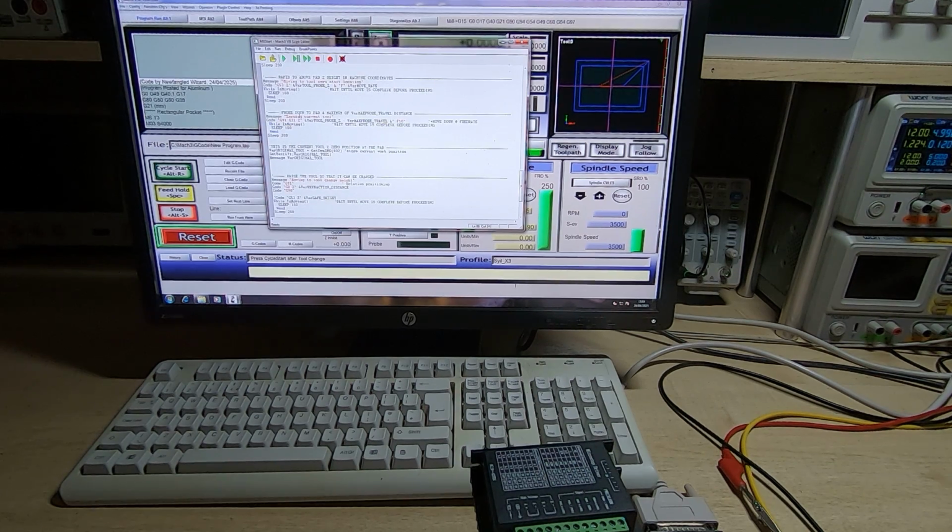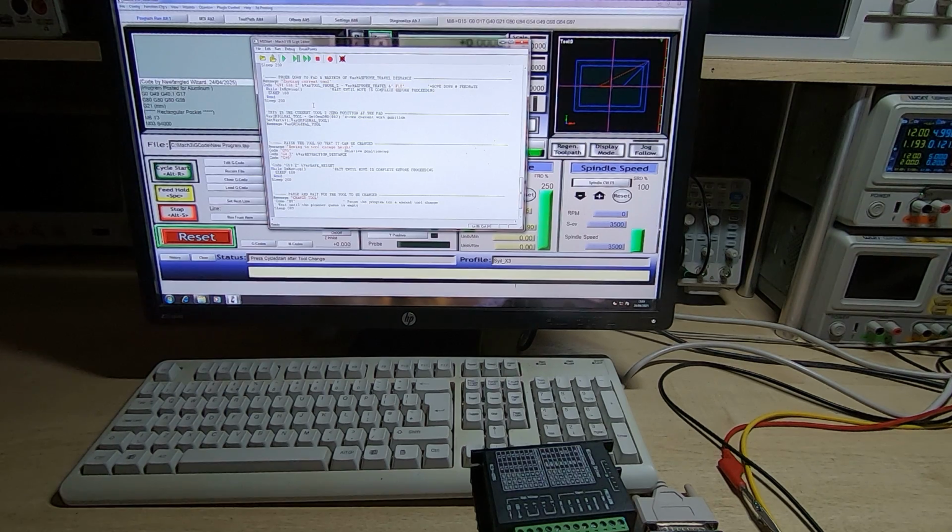It then moves rapidly down to just above the pad, and how far above you move to depends on the expected differences in the lengths of the tools that you're going to use, and again we'll look at this when we look at the actual machine. Once it's got down there, it runs a function within MACH3. This is the G31 function, which is a straight probe, and it probes straight vertically downwards at the speed we've told it to. Again, that was another of our variables.